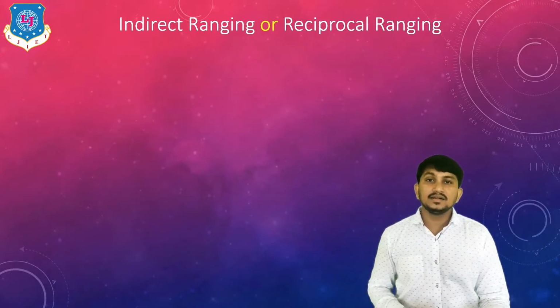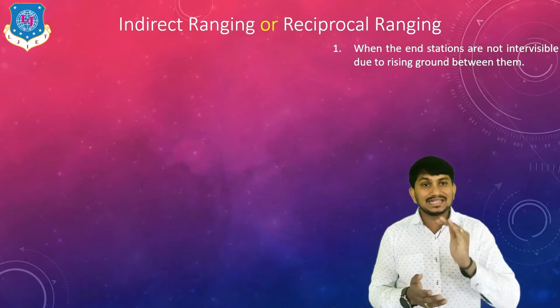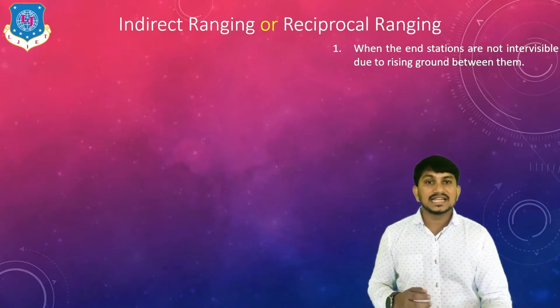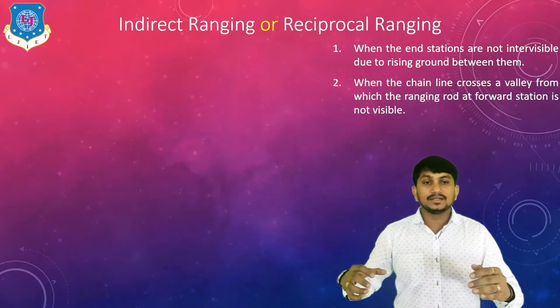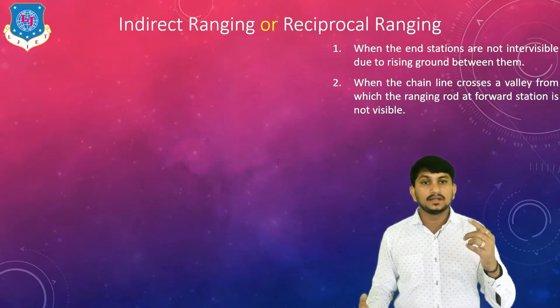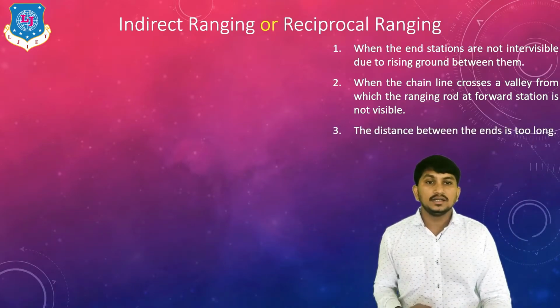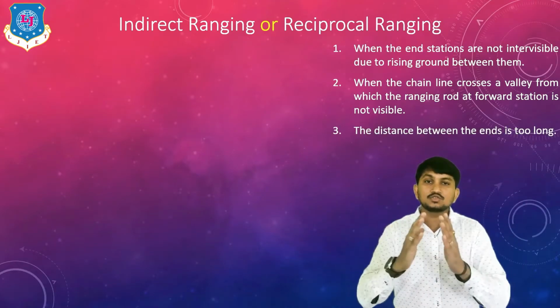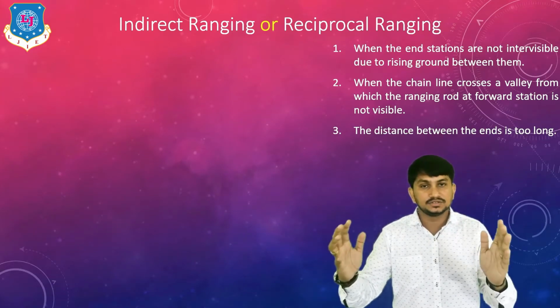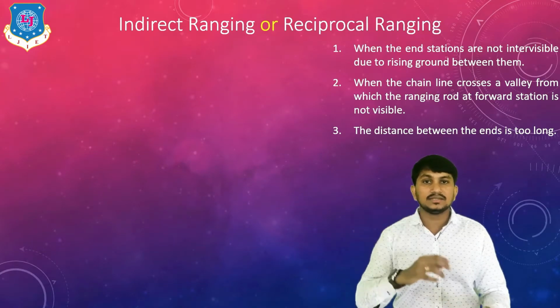There are three conditions where indirect ranging can be used. First is when end stations are not visible due to rising ground between them. Second, when the chain line crosses a valley from which the ranging rod at the forward station cannot be seen at the top. And third, the distance between two end stations is too long to see each other. In these three conditions, we use indirect ranging or reciprocal ranging.